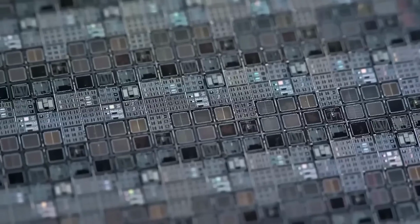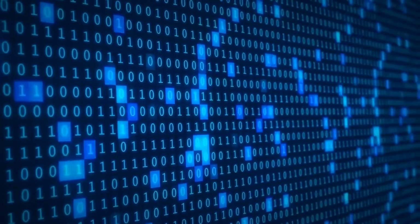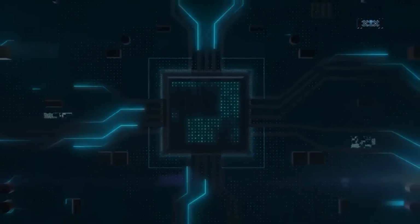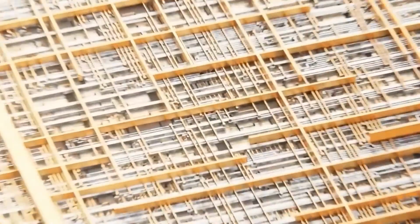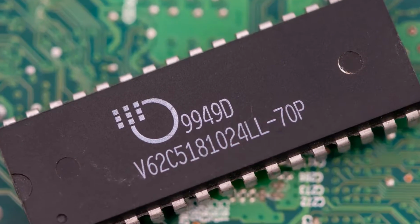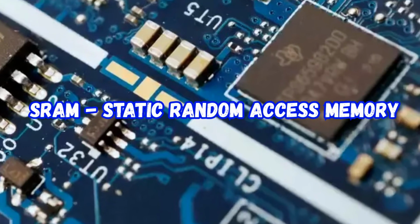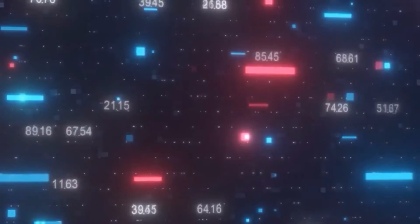In reality, a modern computer needs much more memory, so it is obvious that even from an economic point of view, using only this type of memory is not practical. Furthermore, as we mentioned earlier, semiconductor memory requires constant external power, and it also has a relatively low data storage density, meaning that to store a large amount of data, we would need a device of relatively large size. Therefore, in modern computers, semiconductor memory, also called SRAM from static random access memory, stores only a tiny fraction of the total amount of stored data. It is used for the computer's own memory, such as registers, as well as for the processor cache.